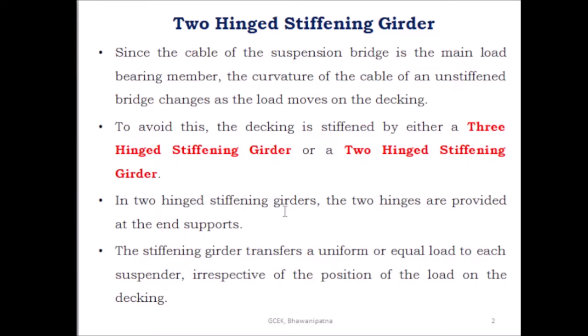Typically, a suspension bridge consists of the following components: the main cable that suspends the bridge deck, main towers that hold the main cable, stiffening girders which are made up of solid girders or trusses and connected to the bridge deck, suspenders or hangers that connect the bridge deck to the main cable, and anchorage to which the backstay is fixed.